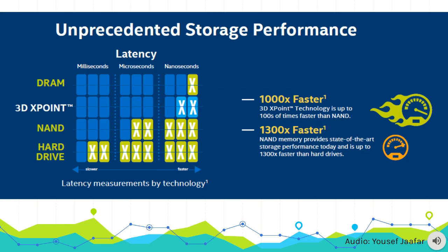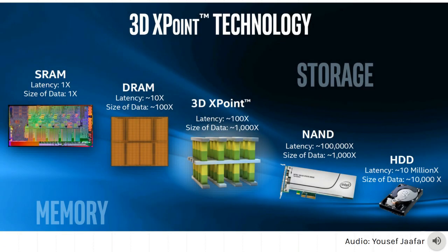So the advantages of Optane SSDs are that they are much faster than NAND memory. They are inexpensive, since they pack lots of memory elements and are denser, which makes them cheap, and they are non-volatile while DRAM is volatile. Their disadvantages are that they are slower than DRAM and still expensive relative to NAND. So in conclusion, this technology will not replace DRAM or NAND, but will work as a midway compromise placed between the two.